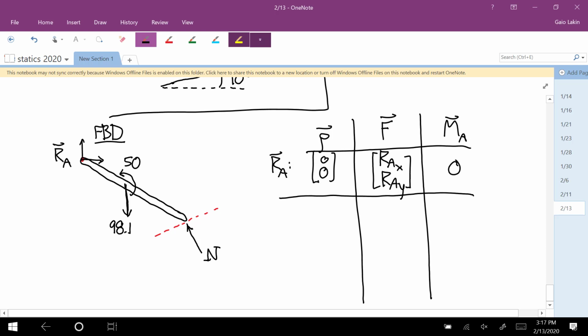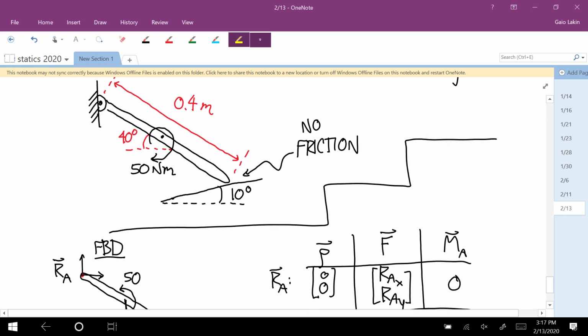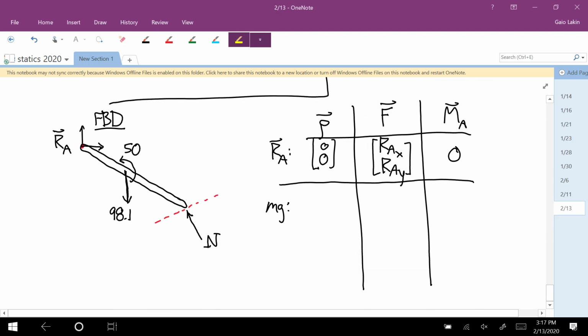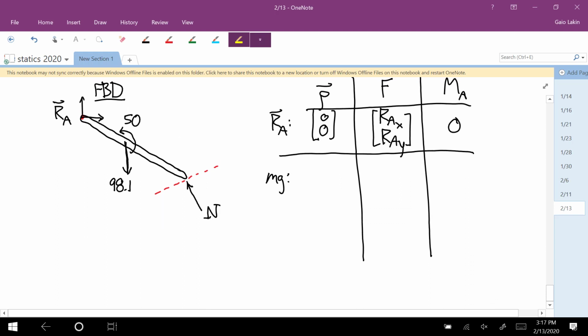And then the weight force, so our row vector goes from that point at the top left to the center. The angle that we have to use there is -40. So it's 0.2 times cosine and sine of negative 40, which is 0.1532.